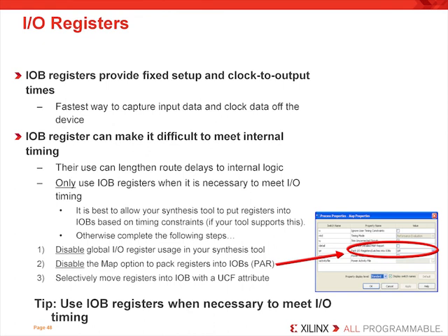First of all, the pin assignments should be near the destination logic. If not, then there will be some internal net delay, and that can be a problem. Depending on the size of the die and the destination, this internal routing delay can become significantly large. So make sure your pin assignments are good. You might even consider making some area constraints to keep that source or destination logic relatively near the pins.